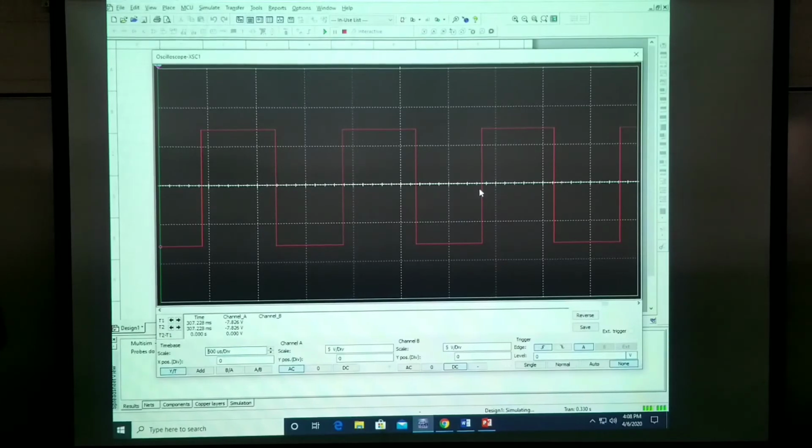So punching it into your calculators, we're going to punch in 1,450 microseconds, so it's going to be shift micro, and then we're going to do the reciprocal to find our frequency.